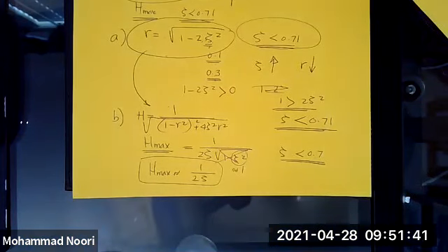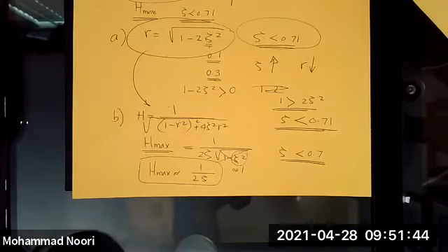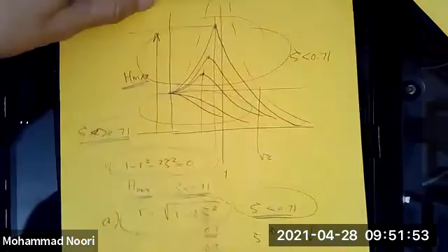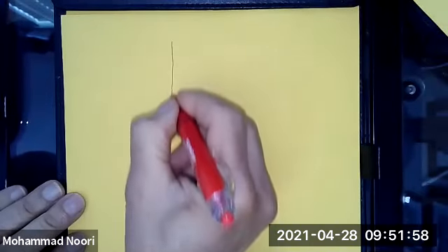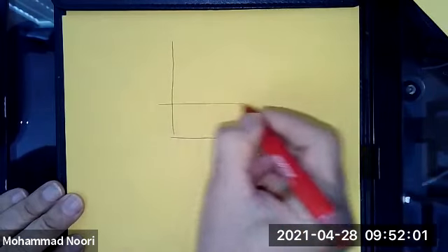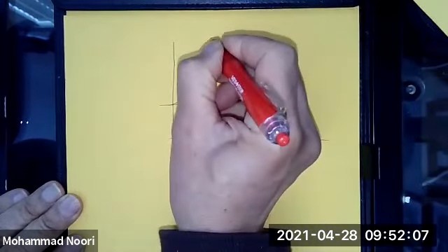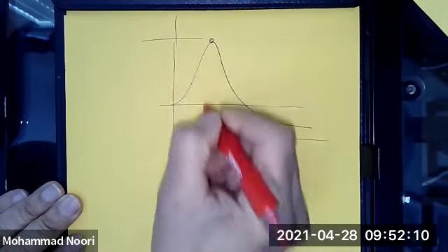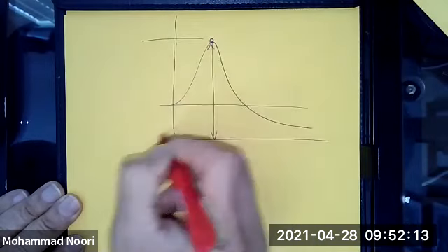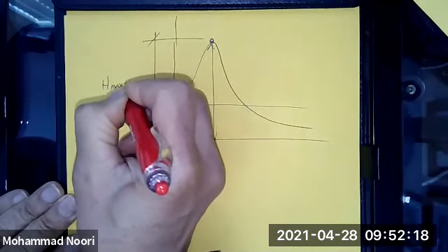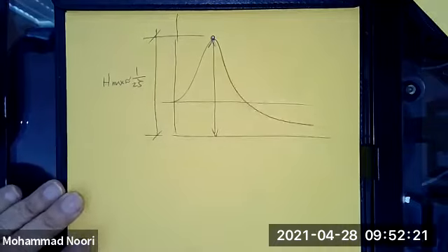In practice, we assign a name to this quantity. First of all, let's look at from the graph what that means. What we are saying is that if, let's say, you have a system, you plot its frequency response function. This is the peak value that you found. This is that peak value. This is H max, which is almost 1 over 2 zeta.